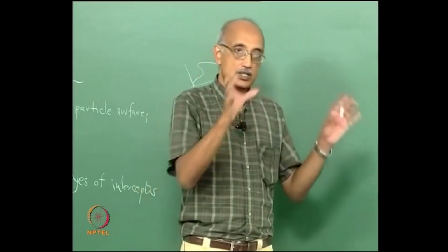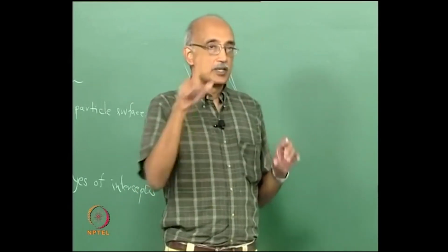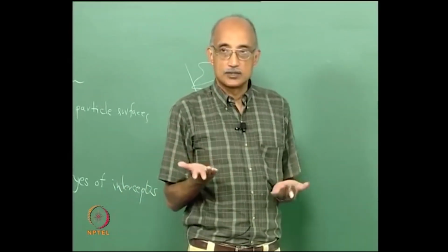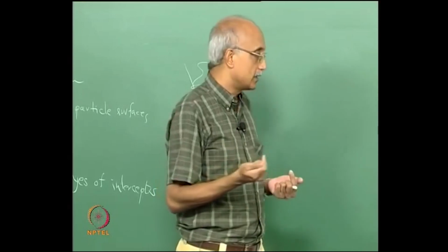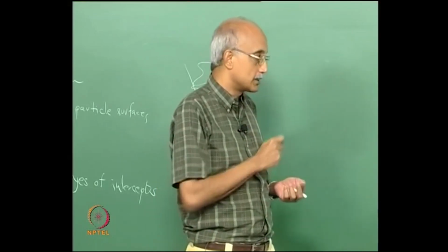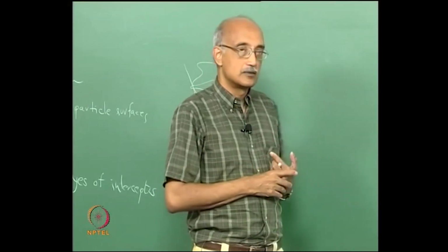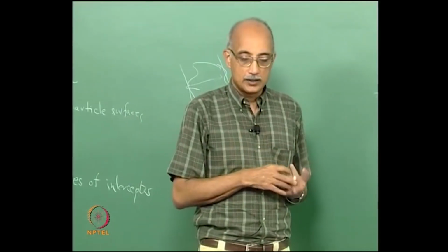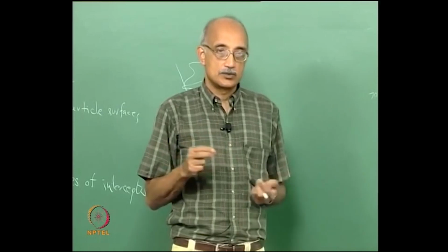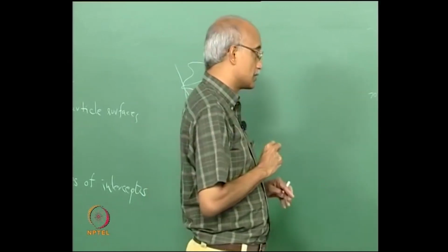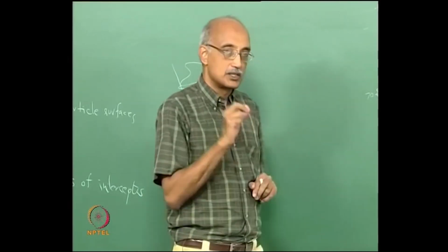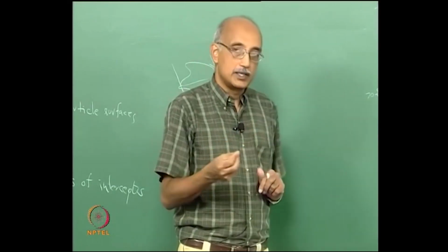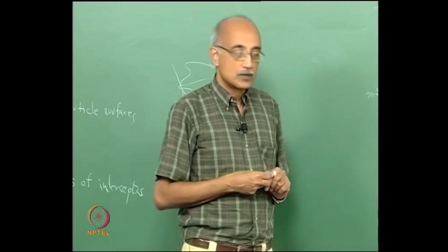You can take this digitized profile and get the best fit polynomial, and you can use that as the representation of the surface. So polynomial fit is another method under this classification. However, we'll see later on that it carries several risks. When you do shape analysis by taking digitized points and doing a best fit polynomial, the error can actually increase as the fit increases.